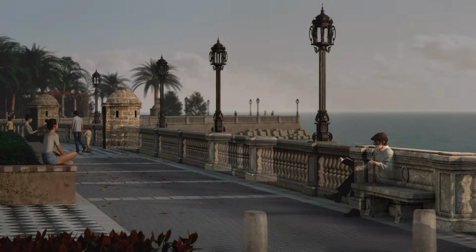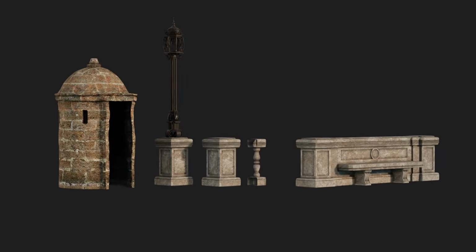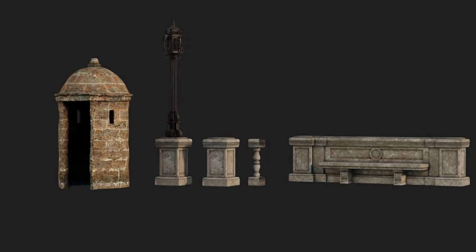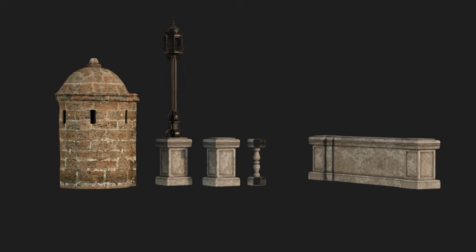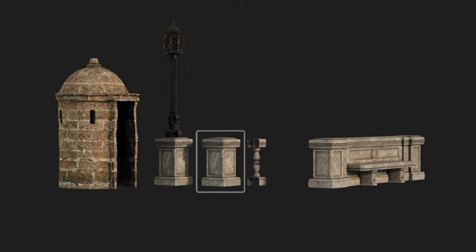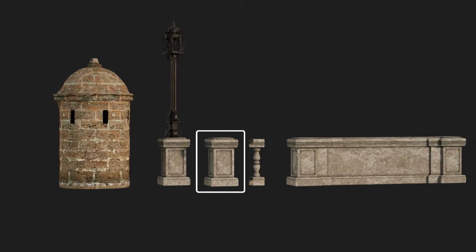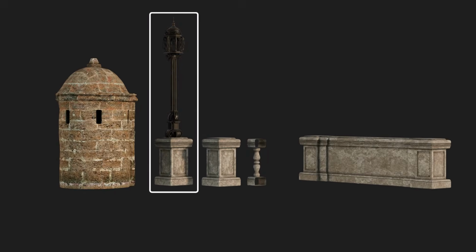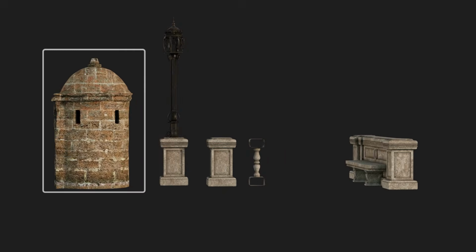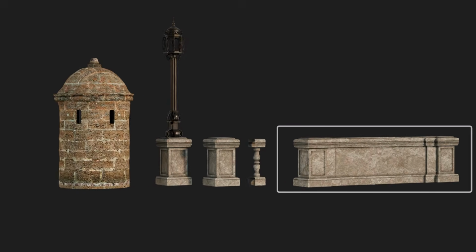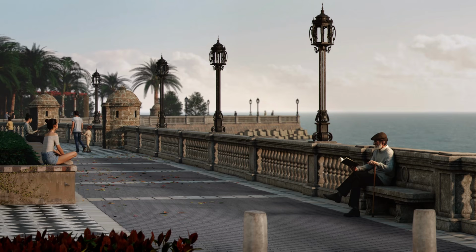Segments are the mesh objects that RailClone distributes along a path. Each one is a piece of geometry from your 3D Studio Max scene. In this tutorial we use several segments: a balustrade, which is the main repeating section, a post which is placed at evenly spaced intervals and at the start and the end of the spline, and a street light which we can use for the same position, a lookout post which will be placed at the corners, and finally a bench which can be placed at specific locations using markers.